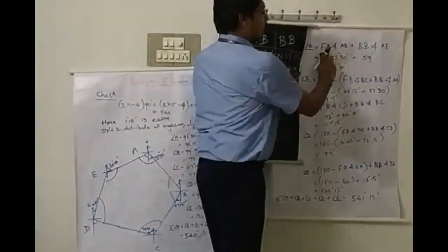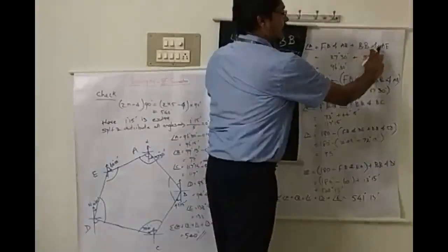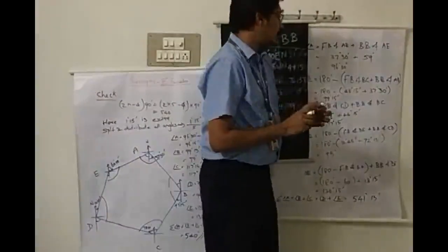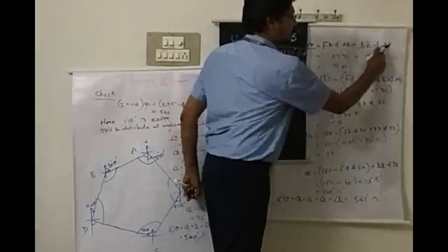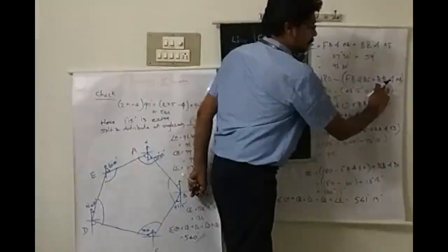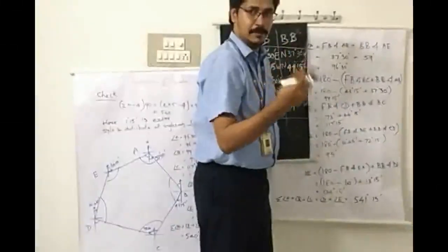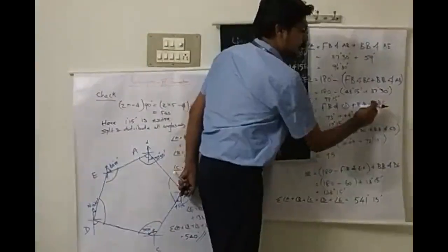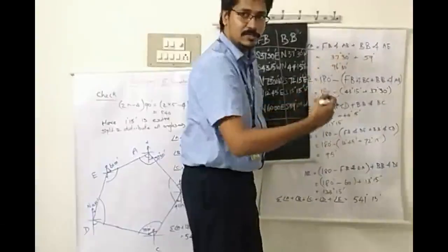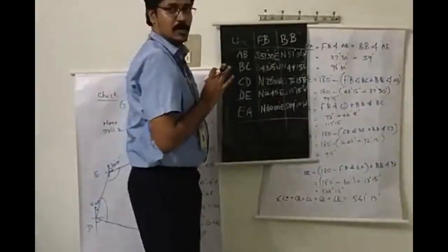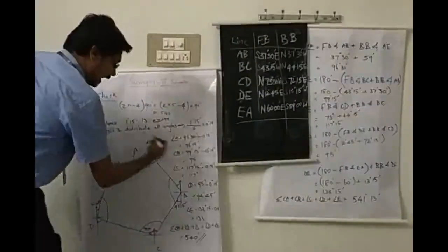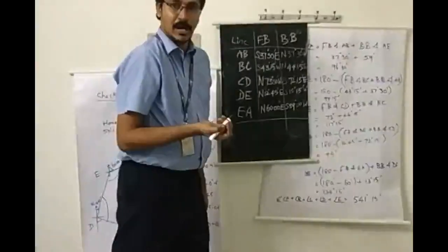Angle A is forebearing of AB plus back bearing of AE. Right? So next is angle B. You can easily remember: here angle A is predominant, next B will be predominant. Forebearing of BC plus back bearing of AB. So B will be repeating. C, CD, CB. Right? Next is here DE, CD. This is the logic behind it when you solve with respect to the reduced bearing. Right? But the 180 minus that, with respect to the diagram you can decide the formula. I hope you have understood.